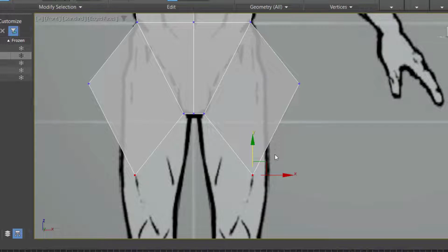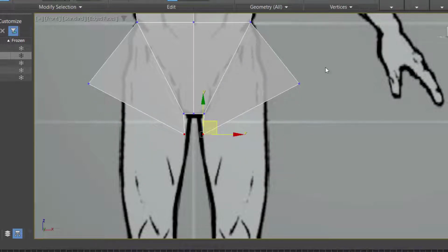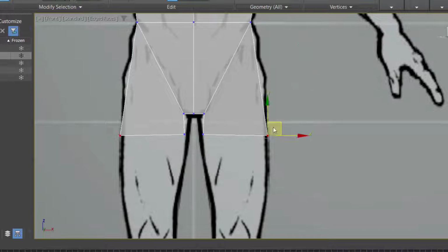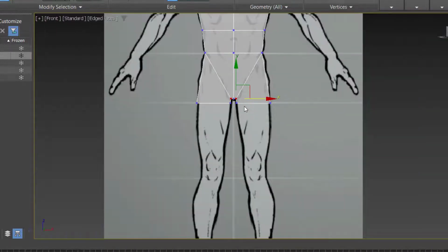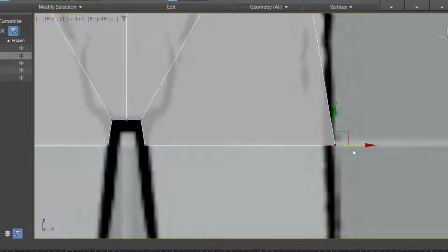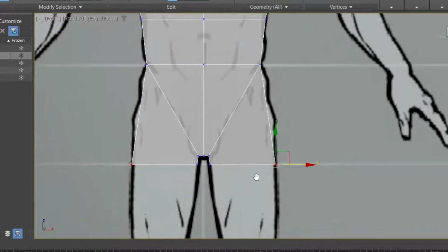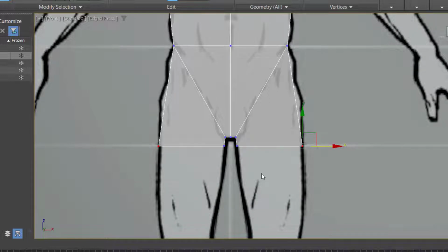So this is what I will do with this. I'll just select the vertices and the other one. I will also select the two of them. Press R. Scale them along only the y-axis. Scaling along the y-axis. W. I'll just drag this. And then this one. Just arranging it. There. Doing this, I'll just Control S to save my work